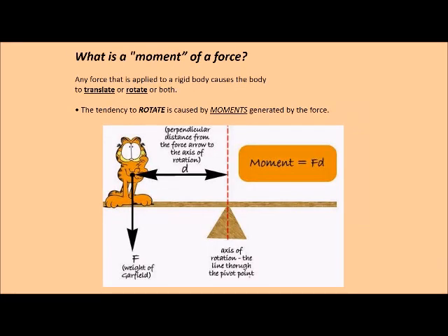What is a moment of a force? Any force that is applied to a rigid body causes the body to translate or rotate, or both. The tendency to rotate is caused by moments, which are created by a force applied some distance from an axis of rotation. This is a really simple cartoon, but these principles are going to apply for all of the problems.